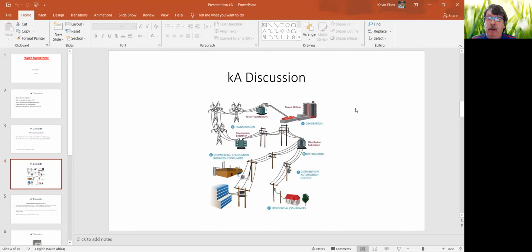And that power is basically determined by things like, if there was just a straight arc, an arc resistance, a resistive base, and there is a theoretical maximum that will be obtained with as low or as negligible a resistance in that equation. Circuit breakers obviously need to handle these types of things. That's what their whole application is.